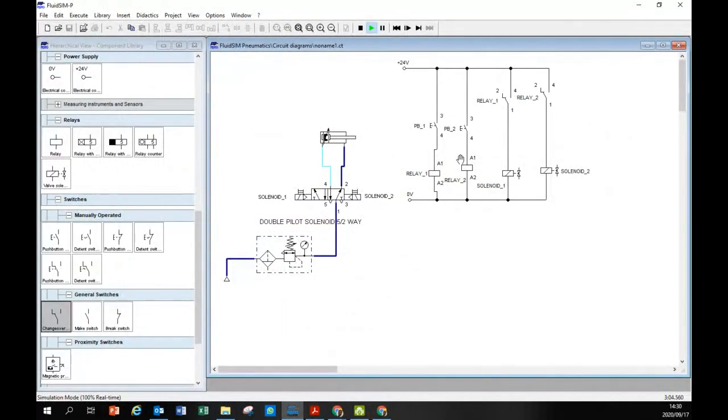I'm just going to amend this for argument's sake. So our push button 1 is pressed. Let's say when the extended end position needs to be sensed, that's how it will return. It will never return with a push button. It will return with a sensor, and that sensor will work by itself. Okay, so that's how we put the sensor.